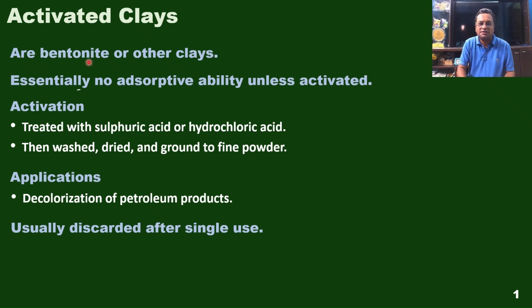So activated clays are bentonite or other clays which essentially have no adsorptive ability unless activated. Therefore, activation is necessary. Activation is done by treating them with sulfuric acid or hydrochloric acid, and then they are washed, dried and ground to fine powder. And the major application for activated clays is decolorization of petroleum products, and there is no regeneration. Usually they are discarded after single use. So that is all about activated clays.